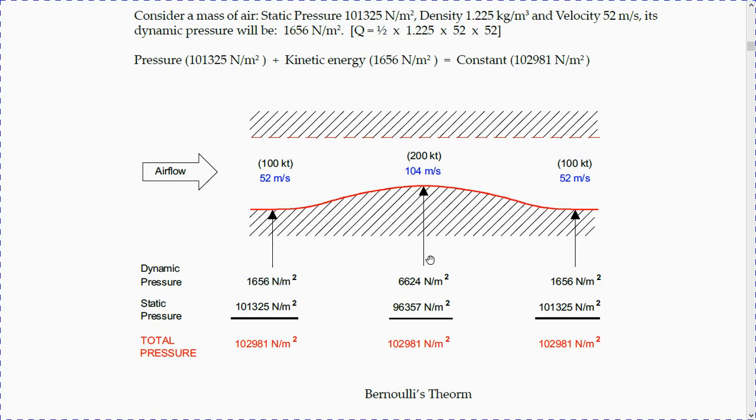So as we can see here, in order for the total pressure to remain constant, something has to change in dynamic pressure and static pressure. So dynamic pressure increases, so speed, dynamic pressure increases, and static pressure now here decreases, so there's a decreased static pressure here. So this is the lift because of this acceleration in dynamic pressure.